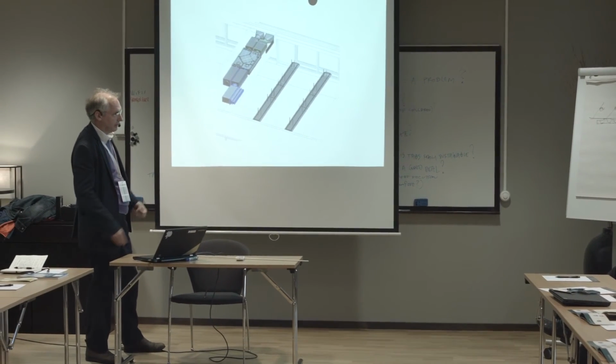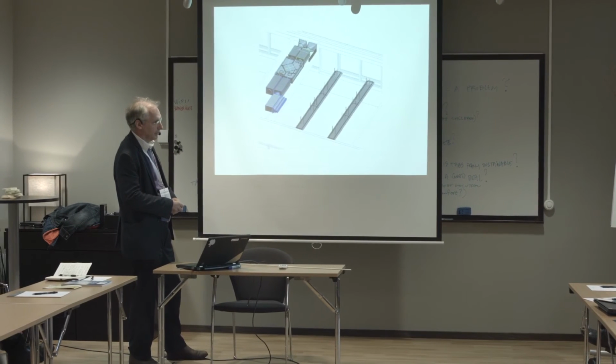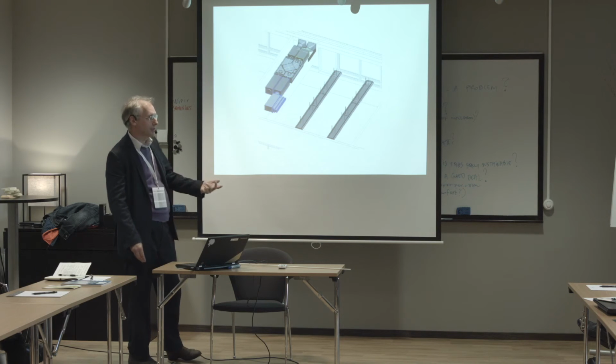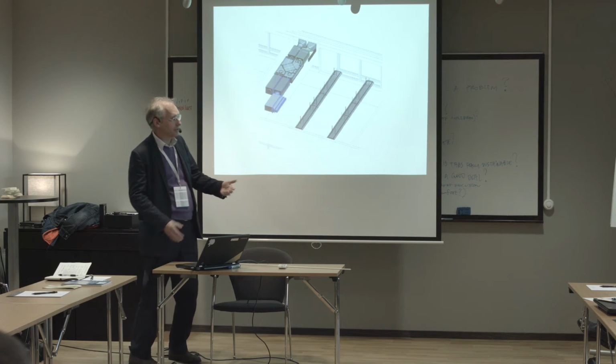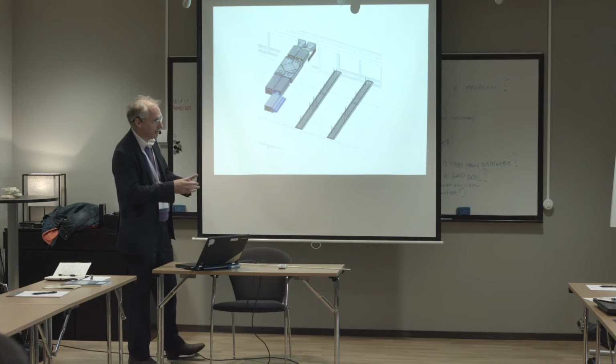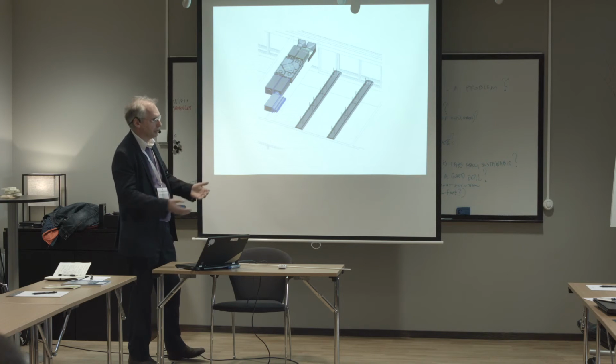Calculating with our regulation the energy performance of school buildings, you always have to implement heat recovery. Yes, well, otherwise you don't meet the requirements. What you get with a premixing system is heat recovery, but it's just not allowed for in the software. The standard software doesn't allow for it. You have to work the software allowing for the heat recovery from the people because we're not throwing it away. It's in the room, so it's not conventional heat recovery.